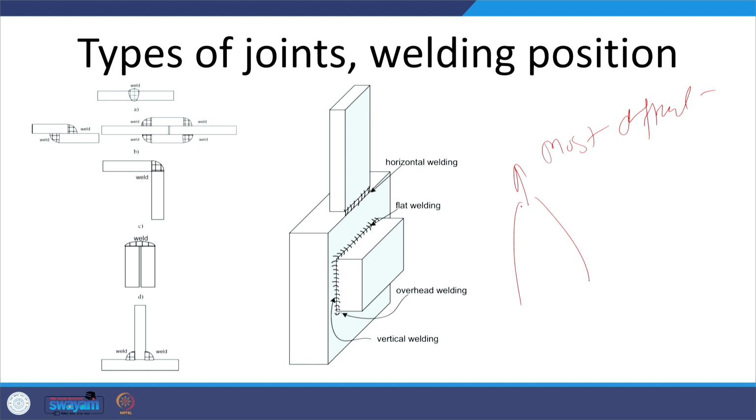Okay. So, say this is the electrode and here we have the arc. The molten metal should be directed in an upward direction to deposit the weld metal. So, this is the location for depositing the overhead weld, meaning the weld metal is deposited in the overhead position. Like in this case, if metal is to be deposited at this location, then it will be the overhead position. Okay.